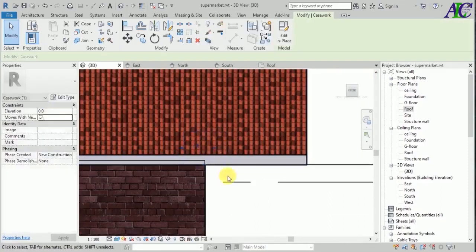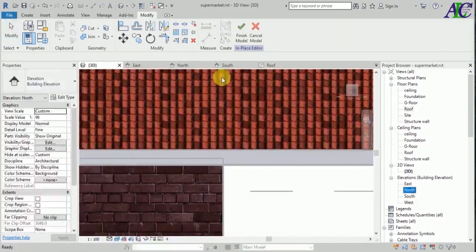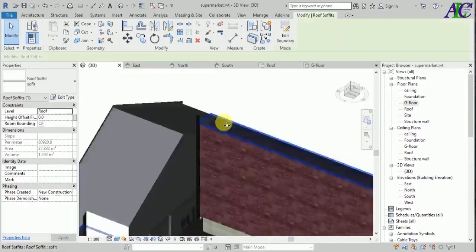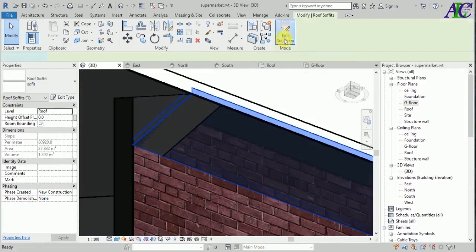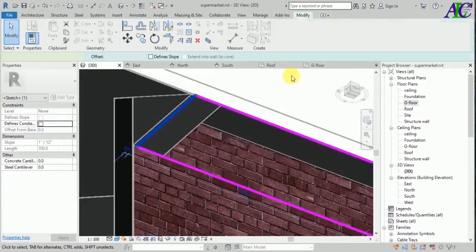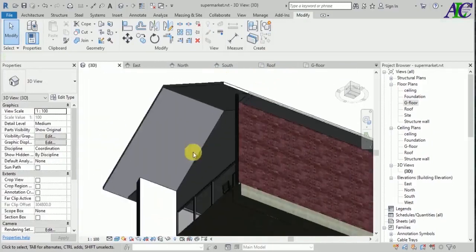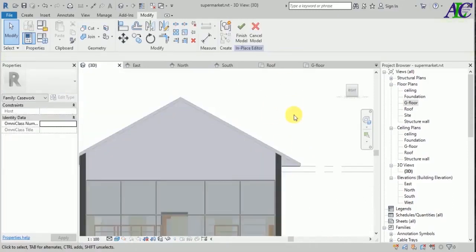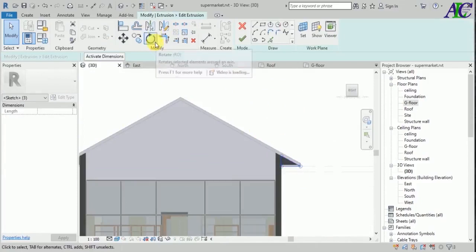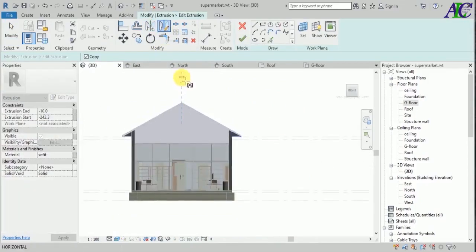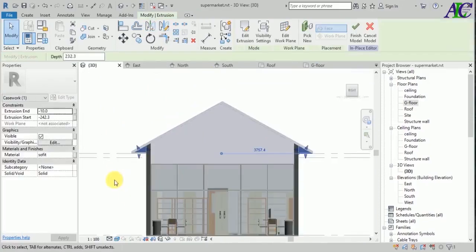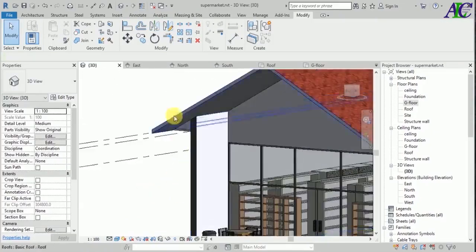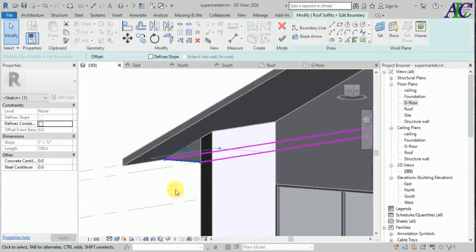So you can adjust now where it should be. Let's move a little bit like this, and again I'm going to edit the soffit a little bit back. Okay, it's aligned to the wall. So now I mirror this for this side. This is how to close this gap as well, and this aligns it with the wall. Okay,